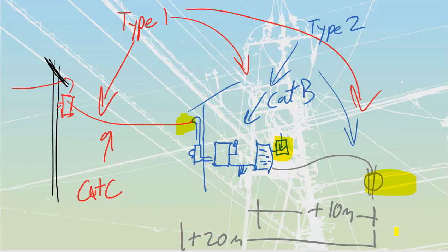What I would get is a continuous attenuation of the amount of let through. This thing cannot prevent everything from getting into the building. There will be some let through, but that bit that's been let through then gets, once again, whittled down by what I've got inside of here, which gets whittled down inside of here. We call that cascading our protective devices.